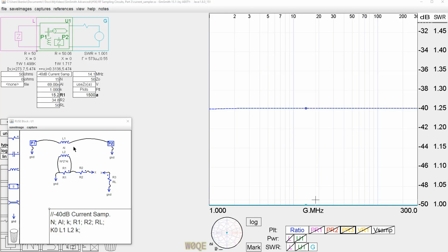Additionally, the current that we have flowing in this circuit is not referenced to ground. Consequently, we need some way to get our output signal back to ground, and a transformer is the device that does exactly that function. Looking at this circuit for a moment, it may seem to be complicated more than necessary,